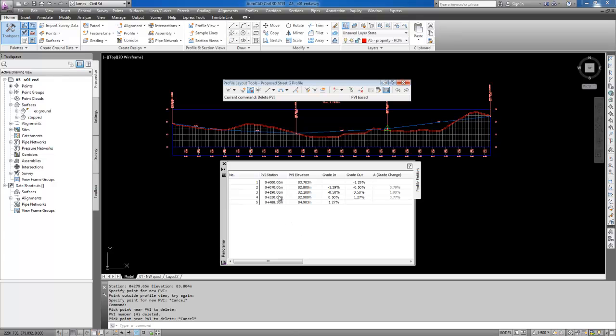So as you can see, all the grades, 1.29, 0.5, 0.5, 1.27, are above 0.5%, and all the changes in grade are either 1% or lower. So your task is to apply this method to the other profiles and complete it. So this concludes video assignment 5, video 2.